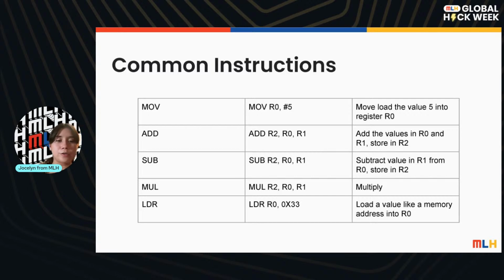No worries. So starting with the add instruction. As I mentioned, each assembly line is a different instruction. So every time you add a new line, you're creating a new instruction. You start with add, the instruction, and it always goes at the beginning. Then you have three elements that go afterwards: R2, R0, R1. All of the R's you're seeing are registers.